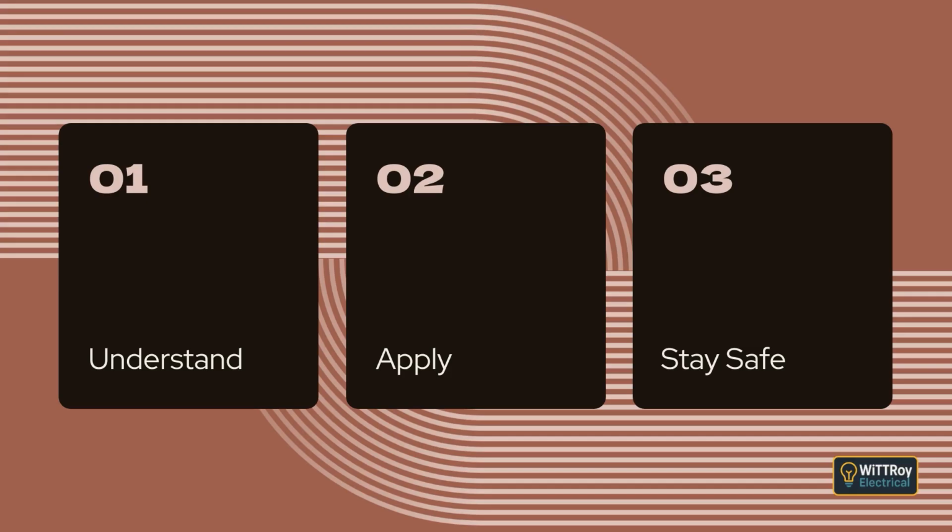Clause 2.3.7.3 Identification. In this clause, the standard explains that functional switching devices do not need to show on or off positions. This is because their purpose is purely operational, not safety related. However, appliance switches must still show the off position so the user can clearly confirm when the appliance has been switched off. The main idea is that functional switching devices do not need formal identification markings unless other standards require it.